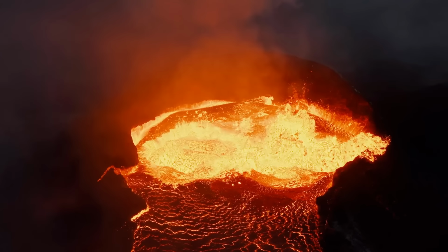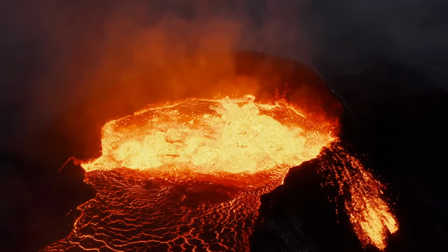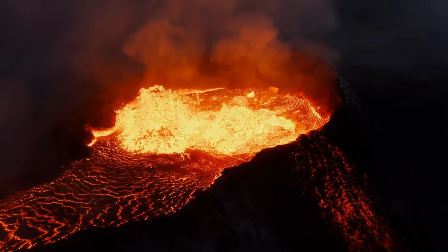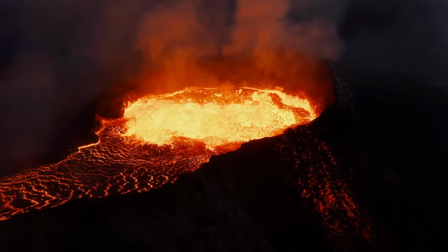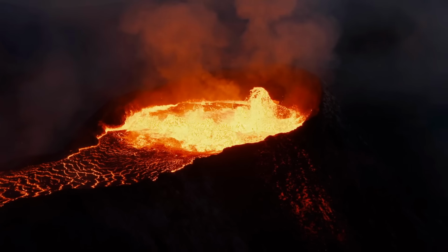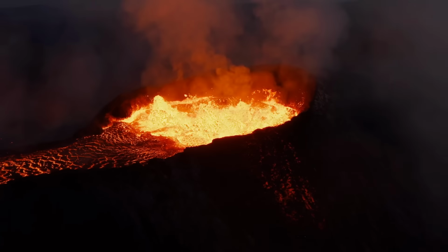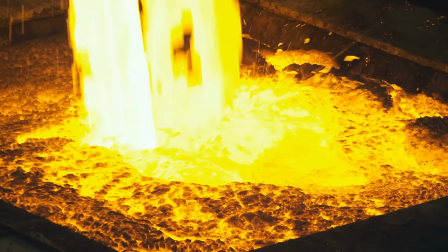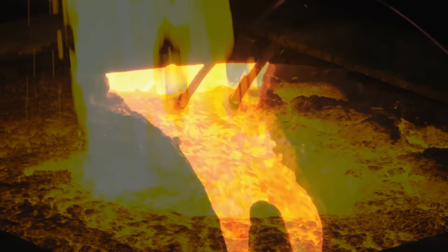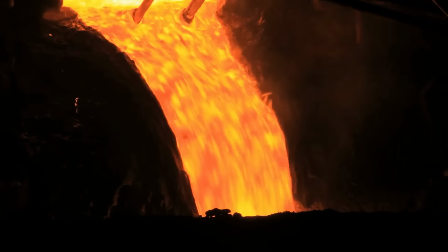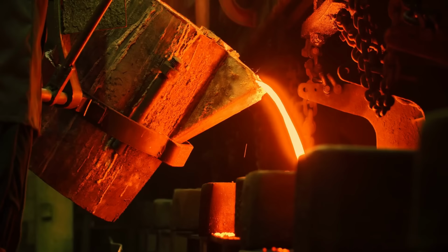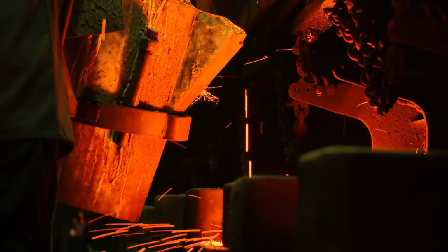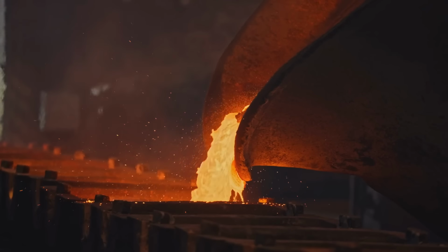The first step is obviously to melt it. The point at which basalt becomes a liquid is called its liquidus point, which is about 1280 degrees Celsius. But to get a good product, we really need to heat it higher than this, up to about 1350 degrees Celsius, so that we can make sure all the particles are completely fused and we get a homogeneous melt. Once this fusing temperature is reached, the melt is then allowed to cool back down to its 1280 liquidus temperature, so that it has as little shock as possible when it contacts the much cooler molds.